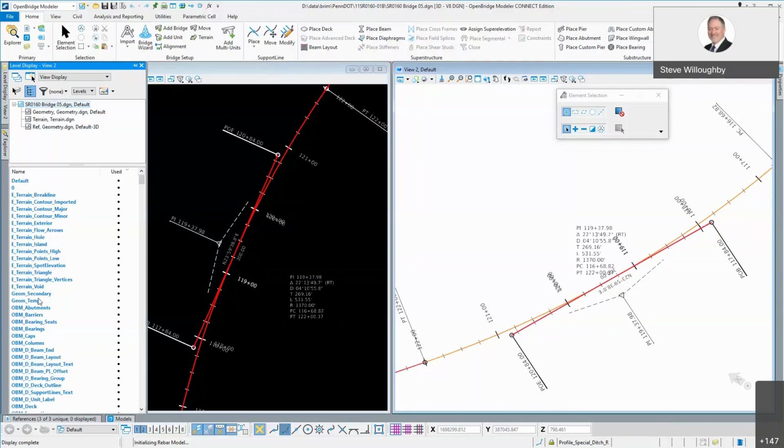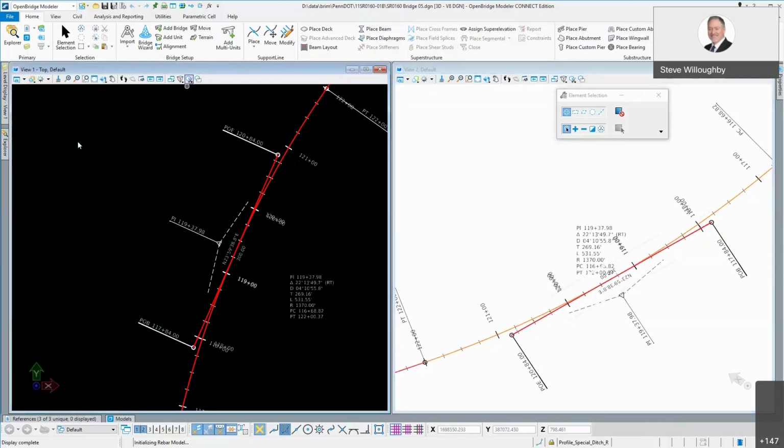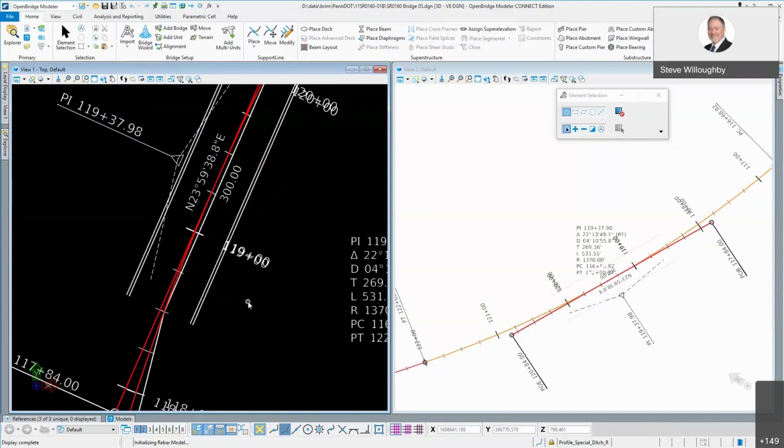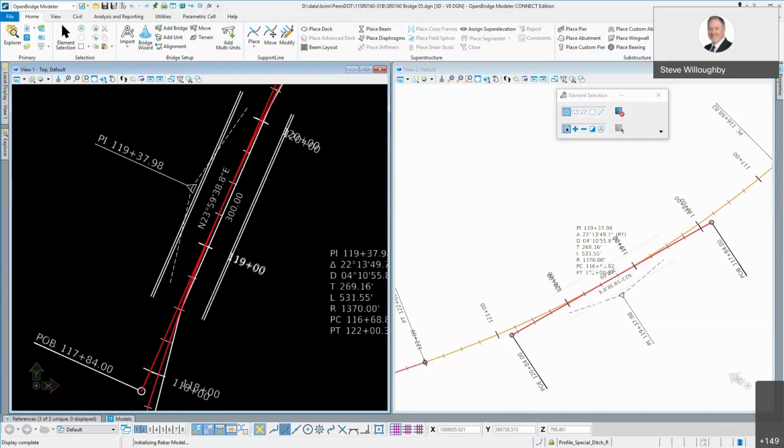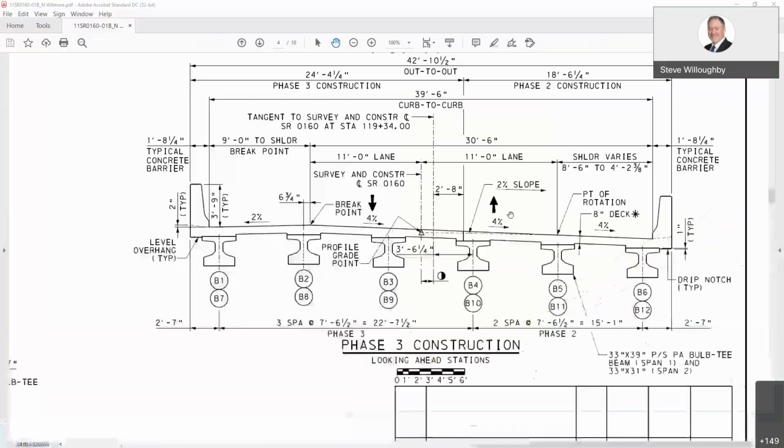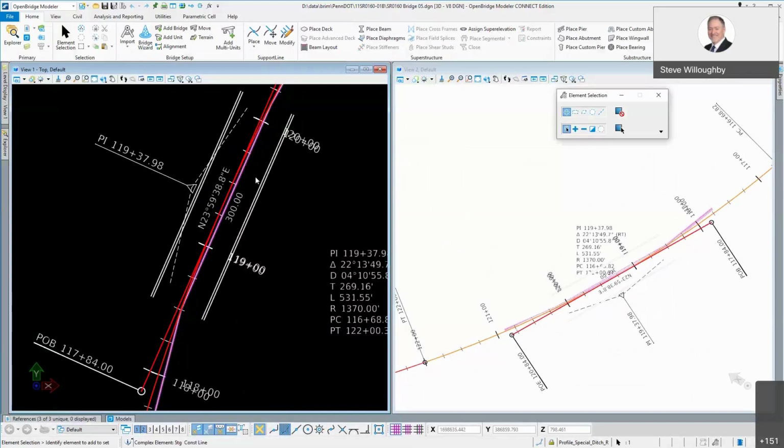So if I go into my levels here, let's turn on those levels in view 1. These white lines right here represent some geometry that I used to tell the software where precisely is this line right here, and then also where is the edge of deck. More importantly, I didn't really end up needing to use the edge of deck one, I ended up using this flow line here, and I'll explain why in a moment. So for this line right here, if I select it, you'll notice it's 2.667 feet off of that local tangent, which is that 2 foot 8 inches that I was given.